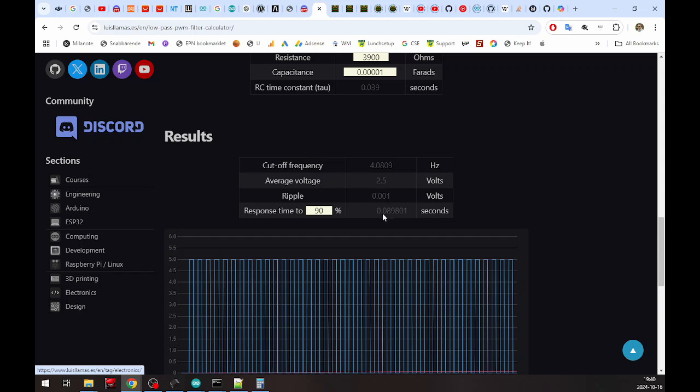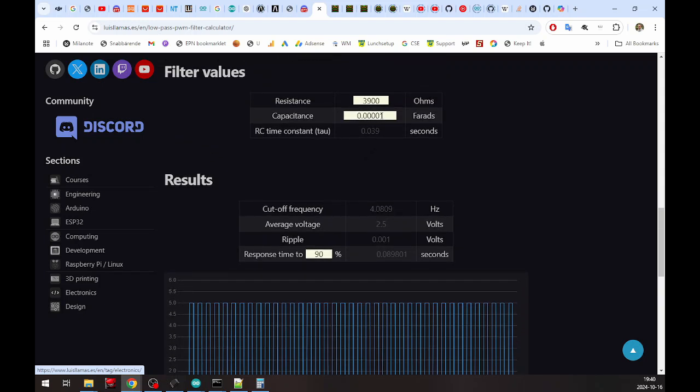And let's say we want to do an ADSR, which is my next project, that is definitely fast enough. If it's not, I guess we can go down a bit. So here we can see 200, then it goes up. So if we go down to 50 nanofarads, 0.5, then 0.05 seconds, which is good.